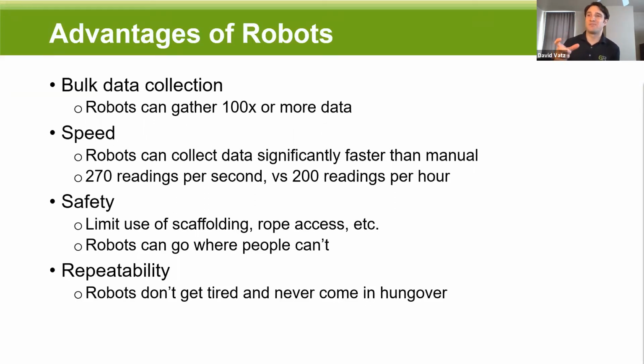We usually look for 7 or 8 inches of clearance, so we can get under things like scaffolding if you do have scaffolding erected. For a digester shell, we do most of our digester shells with no scaffolding at all. We'll talk about this in one of the case studies. We'll actually launch the robot from the flange without putting anybody inside of it. But yeah, 6 to 7 inches is about what we need to get under something.